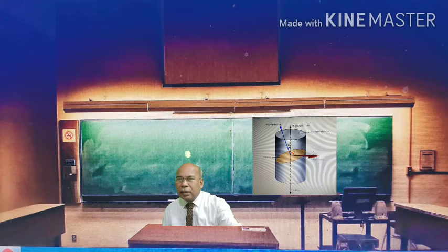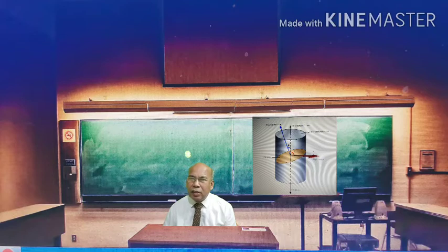The direct stress can be resolved into two components: a shear component and a normal component. Slip takes place along the direction of the shear component. This is called the slip plane. The direction is called the slip direction. The whole system is called a slip system.